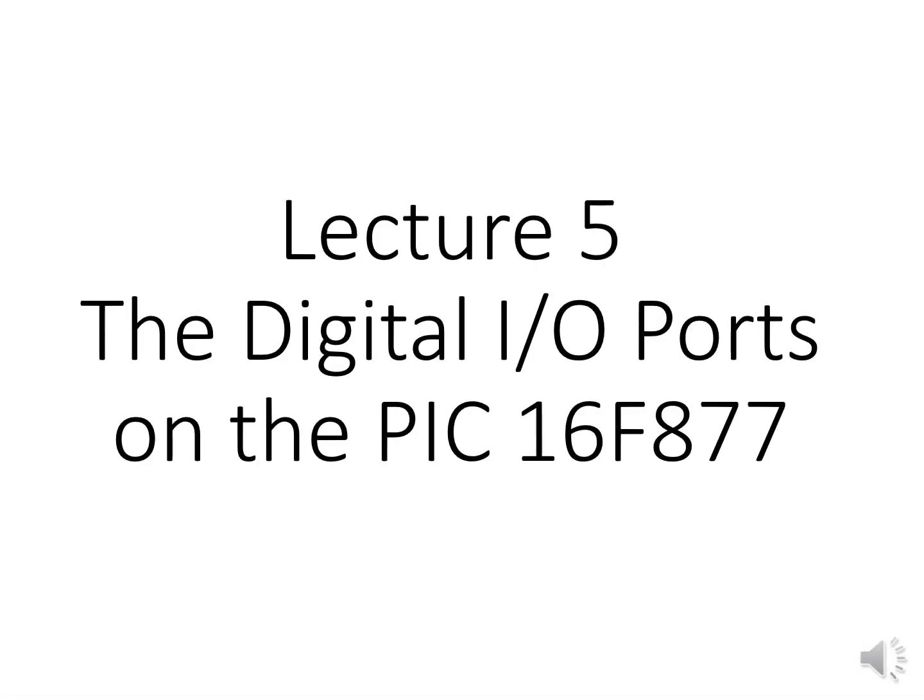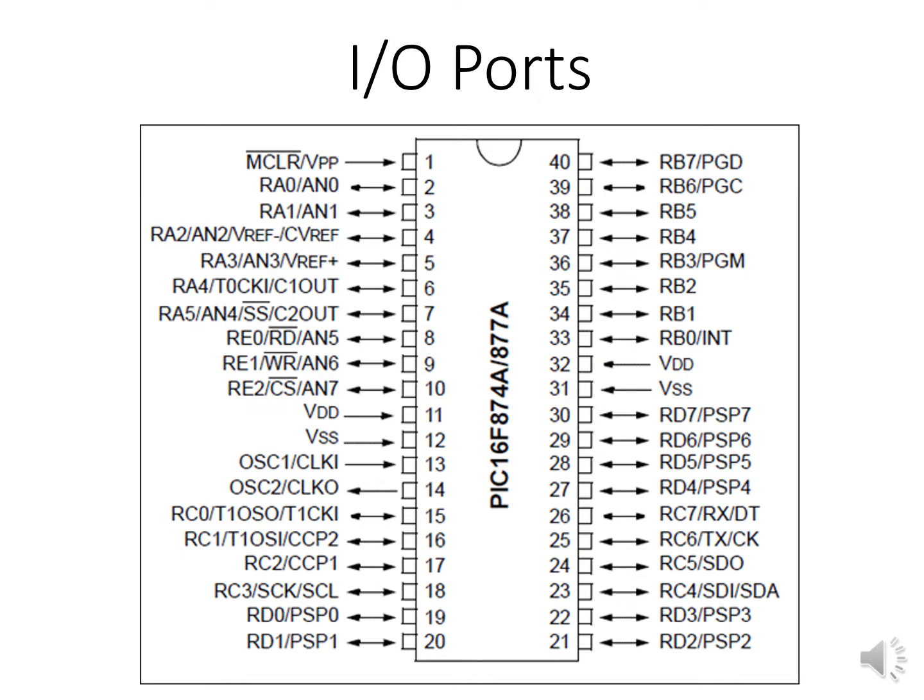In this lecture, we are looking at the digital I/O ports on the PIC16F877. The PIC16F877 has 33 digital I/O pins. These pins are distributed into 5 ports, and these 5 ports are named Port A,